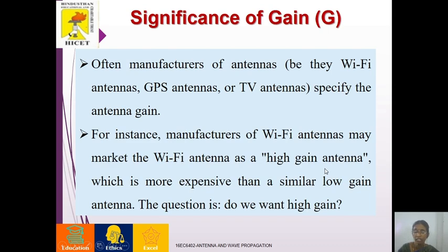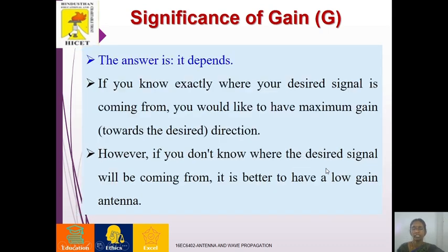So we have to decide, do we really require a high gain antenna? The answer is, it depends. If you know exactly where your desired signal is coming from, you would like to have a maximum gain direction towards the desired direction. However, if you do not know where the desired signal is coming from, then it is better to get a low gain antenna instead of a costlier high gain Wi-Fi antenna.